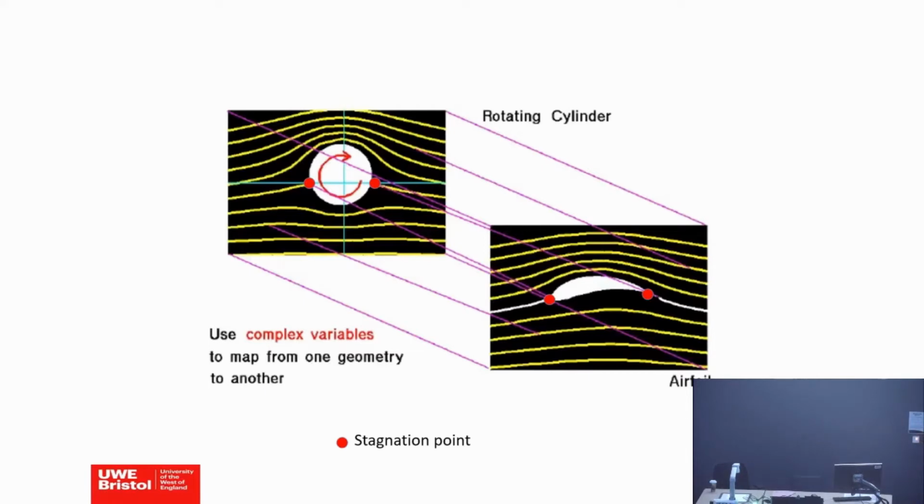we want an airfoil, we want a lifting flow, right? We want the lift to be generated. So the picture on the left is what we did before. That's the potential flow around a lifting cylinder or a rotating cylinder. So as before, there is flow asymmetry, top and bottom. Therefore, I know there is a lift, okay? And the stagnation points as before at theta equal to 0 and theta equal to pi. So that's fine. We can do that with potential flow theory.